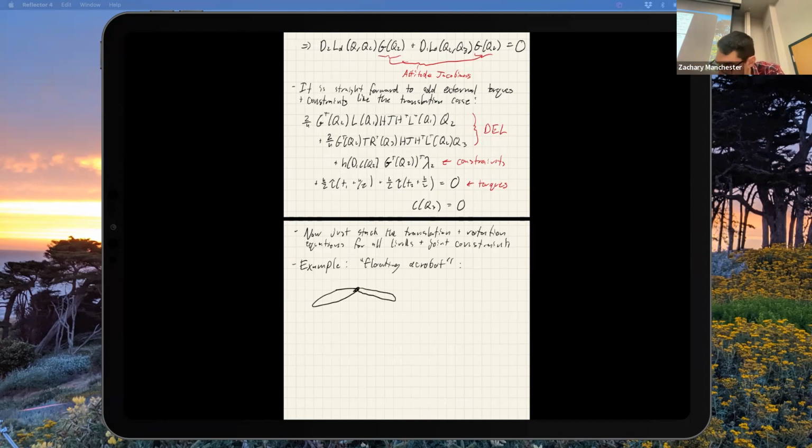And we've got a CG, and I'm going to define these vectors from the CG to the joint on both of these links, like we talked about. So this one will be B1, and this one will be A2. And this link has position R1, attitude Q1, and likewise over here. Okay, so how do I write down the joint constraint?